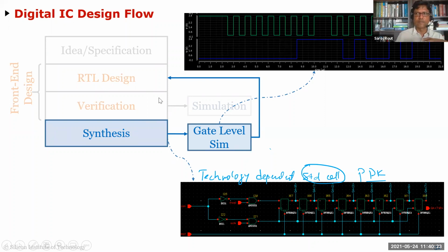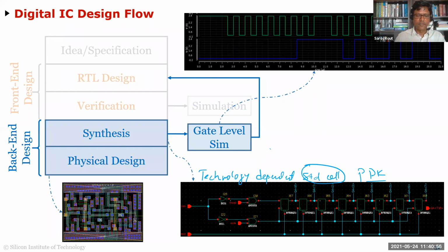Formal verification is basically a mathematical tool which will take your gate level and your behavioral level and it will say, yes, 99% probability that these two are similar in nature. Gate level simulation is 100%. If your gate level is agreeing with your simulation, then you're 100% correct. Whereas with formal verification, there's still a probability. But for large designs, that's usually a crucial step, because gate level simulation will take you days to do. Okay. And if you're happy, then you go to the physical design process.